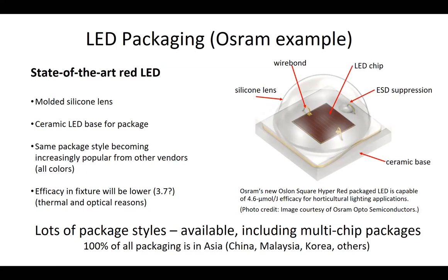So if I had to make just a gut guess, we're going to see gradual increases in the micromoles per joule for the overall LED fixture from the vicinity of the high 2s into the low 3s, but probably no more than about 3.2 to 3.5 over the next 5 to 10 years, just because it's going to be really hard to make really efficient drivers and have very good thermal management, with the possible exception of water cooling in greenhouses. And there are some people making water cooled fixtures. The driver losses aren't built into that number.